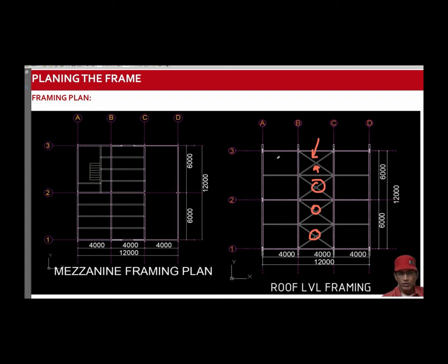So in the response spectrum method, there is a CQC method to work out the base shear. Base shear is the total seismic load that will be generated during a seismic occurrence. In the CQC method, the signs are lost, and to use tension members, we need to preserve the signs.